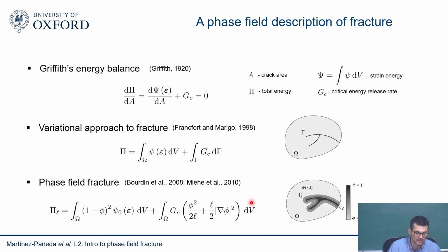The other thing is that it's a non-local continuum damage mechanics model. And that's the issue with continuum damage mechanics modeling: first of all, it doesn't link to fracture as phase field does, but also normally models are local, which means they are mesh dependent. Here, you get a non-local continuum damage mechanics model where you have a gradient, and because you have a gradient, due to dimensional consistency, you bring in a length scale. And this length scale plays a role in multiple ways. We'll discuss them later on.